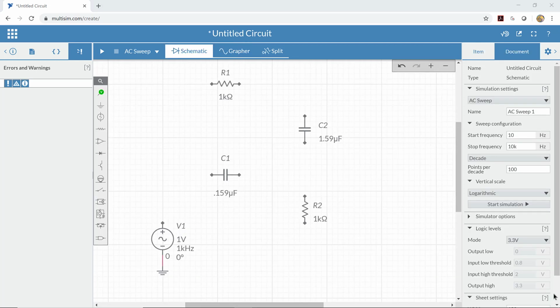Now we're going to talk about how to create a bandstop filter that rejects the frequencies between two particular points. So for the sake of simplicity, I'm going to choose the same cutoff frequencies that I had before, 100 hertz and 1 kilohertz. But now I have to build a low-pass filter with the cutoff frequency of 100 hertz.